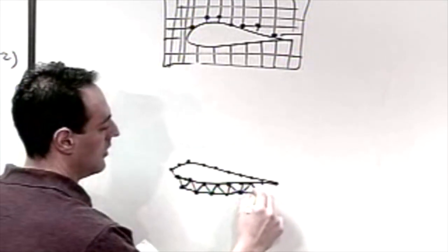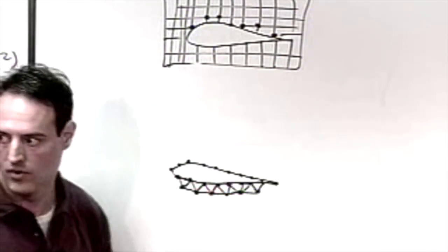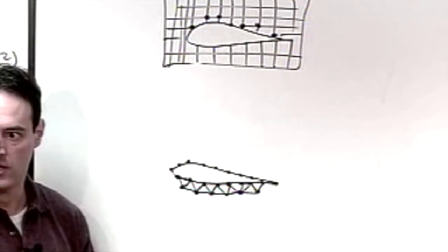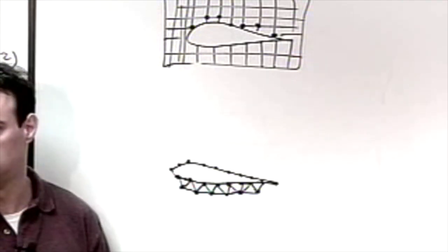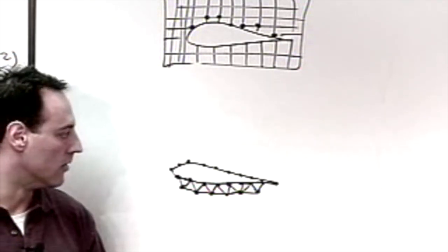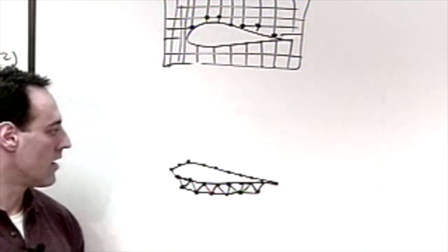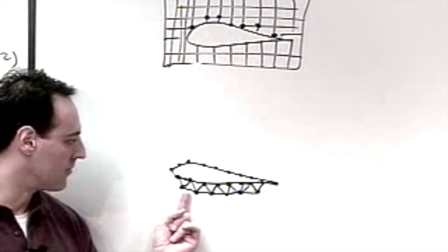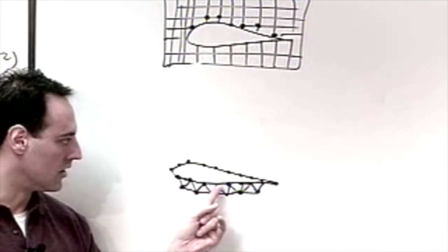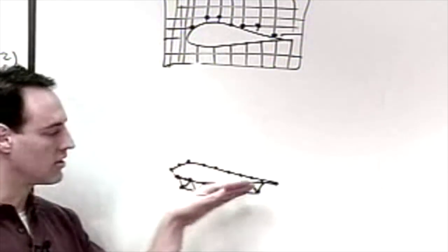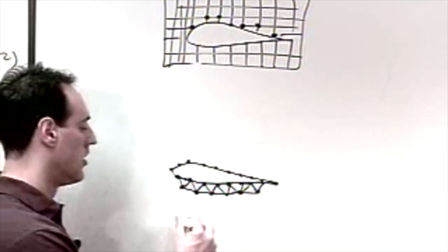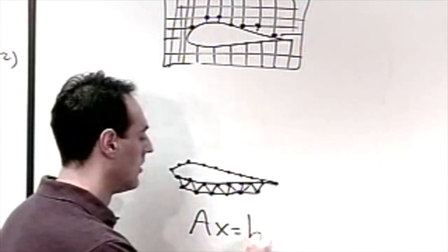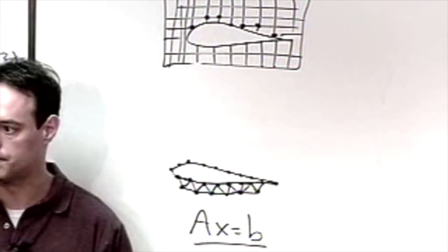Anyway. Okay? This is kind of the basic idea of this thing. To make a grid or a mesh that actually conforms to your boundary condition versus trying to make your boundary conditions conform to your mesh. Okay? It's a different philosophical point of view. So this is kind of what you're really going to do, is you're going to use some approximating functions in here, which are these triangles, connected to this region. And in the end, what you have to solve for is all these points. Every point, and so eventually it's going to be, again, a big old Ax equals b solve again.